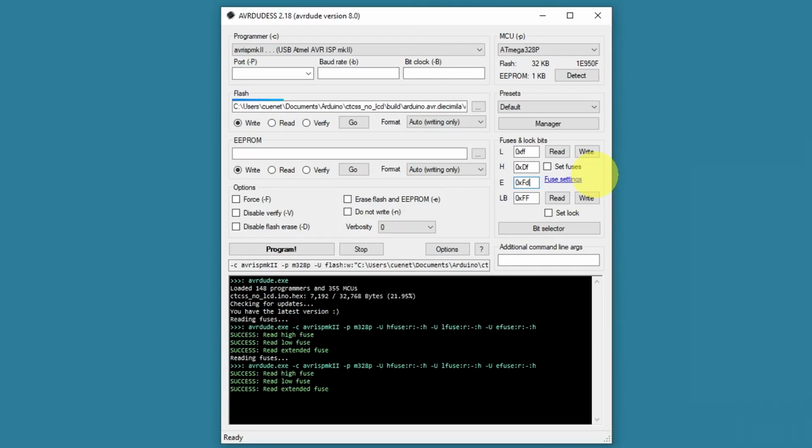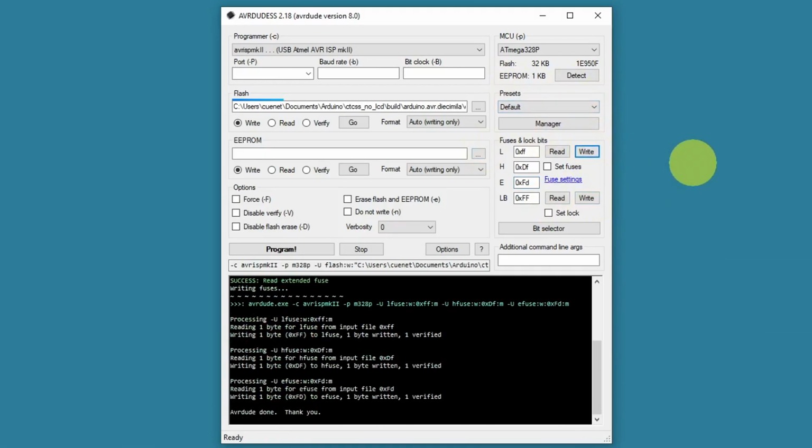Also for anything over 8 megahertz. Well, that's correct, because we're running a 16 megahertz clock. So what we need to do now is write those to the chip. Let's do that right now. Okay, that's now done. Hopefully, if everything's worked, our device should be clocking at the correct speed. When you reset the unit, it should only take a couple of seconds, and you should have a display straight away after the splash screen. I think we've got it set to 3 seconds at the moment.